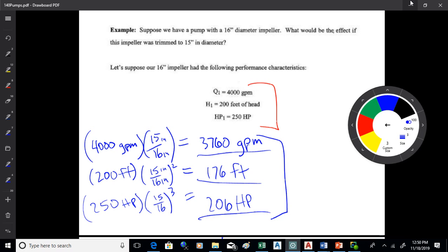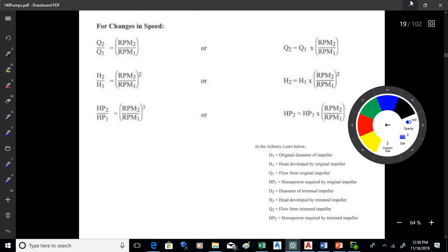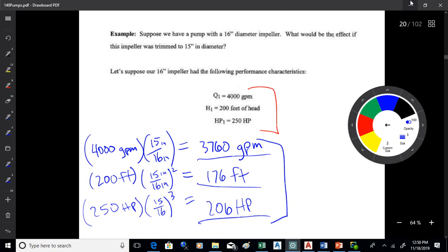Now, my question there would be, could you just put a smaller motor on without changing the impeller? Smaller motor, you're going to get less horsepower. Yes, I think you could. This might be a cheaper fix. It's just dependent on what you've got available. This tells you about two effects, motor RPM and also the impeller size. I have seen pump curves, which is data about a pump that you get, that will have 3 or 4 different impeller sizes on it. You can buy a pump with different size impellers, and so they do affect the performance.